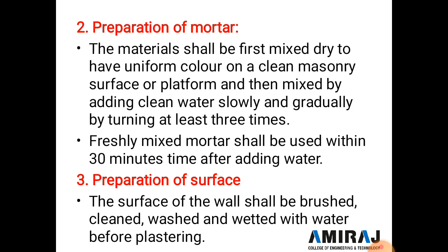So first we do a dry mix, and then after adding water we mix properly. This mortar is used within 30 minutes because after 30 minutes the cement starts to gain strength and becomes hard.